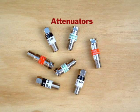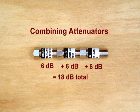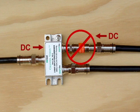Let's start with attenuators. These are used to lower the amplitude of a signal. They typically come packaged in a barrel shape marked with a dB attenuation level. You'll find these commonly in 3, 6, and 10 dB versions. You can screw them together to achieve any amount of attenuation you need. They aren't made to dissipate any power, so they should not be used where there's a DC voltage on the cable, since they'll get hot and possibly burn out.